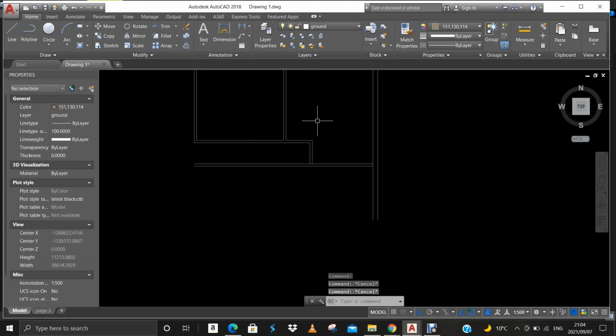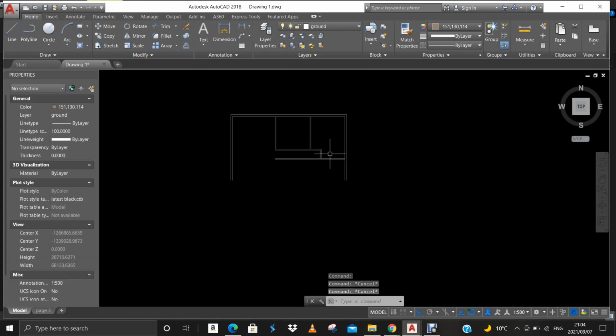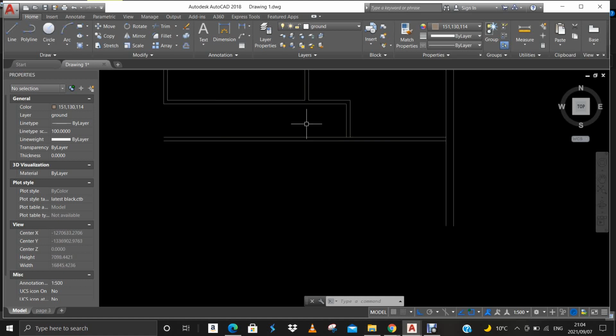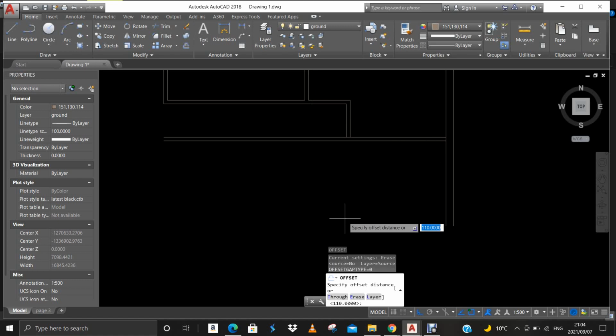So now I've got my main bedroom, which is a bit bigger than that one. It's about 5 meters this way and 4 meters that way. This one is a 4 by 4. So now here I'm gonna use this side as my bathroom. So now I want it to be in line with that, but I know it's 4 meters. So I'm just gonna offset 4 meters